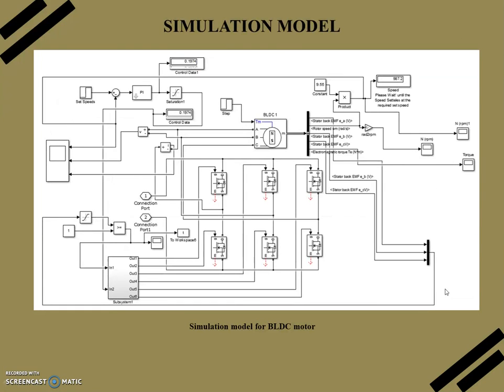In this project, as the load I have used a BLDC motor. In a BLDC motor, torque production takes place through attraction and repulsion between the stator and the permanent magnet in the rotor. When these fields are at 90 degrees, the maximum torque production is possible. So to energize the correct stator winding, the rotor position must be known. For this, we have used a Hall effect sensor.